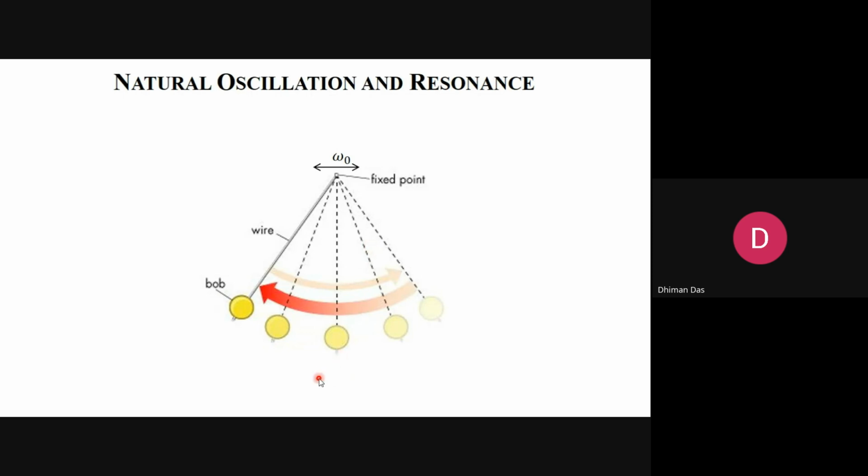If you take any kind of system, say a spring mass system or an LC system, if you trigger one LC, you will get natural oscillation at 1 by 2 pi root LC. But after a certain time, the oscillation is going to decay because of the resistive element in the system. The power of the oscillation will be damped into the resistance, absorbed by the resistance.